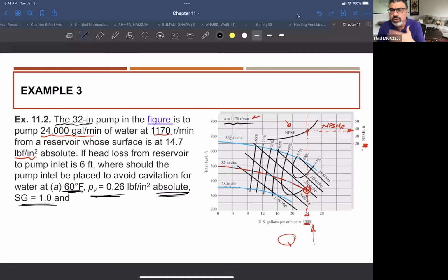Positive displacement pump is not all the time a solution, right? But I agree with you that there is no cavitation. No, in this case you can still have cavitation in the positive displacement pump, as long as you are reducing the pressure, because when you are sucking the fluid, sucking means you are reducing the pressure at the inlet. So in this case, you still have a negative pressure. In the positive displacement pump, you still have suction, and in the suction action, you have negative pressure.